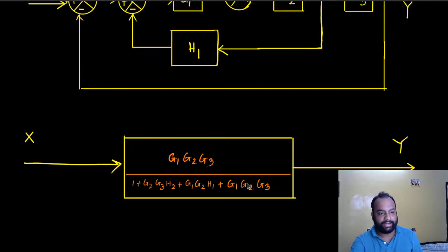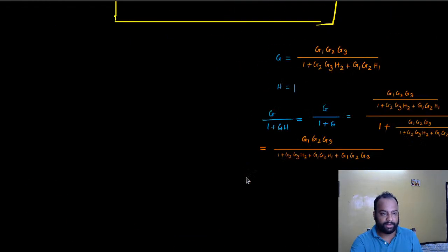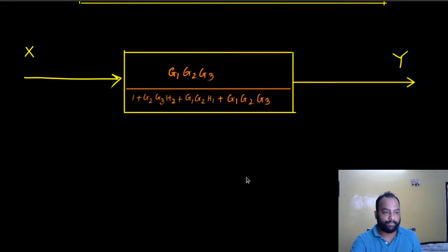So this is one of the techniques that we use, known as the block diagram reduction technique. But just to make sure that you understand this very well, you have to understand that we did not apply any formula per se other than the cascading series combination, the parallel combination, and the feedback combination.